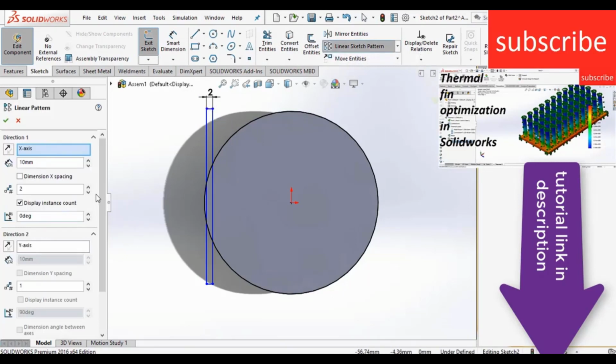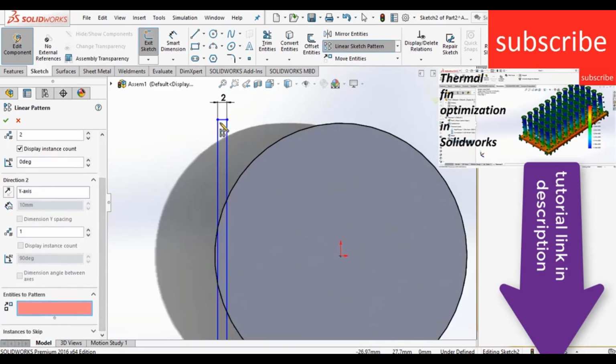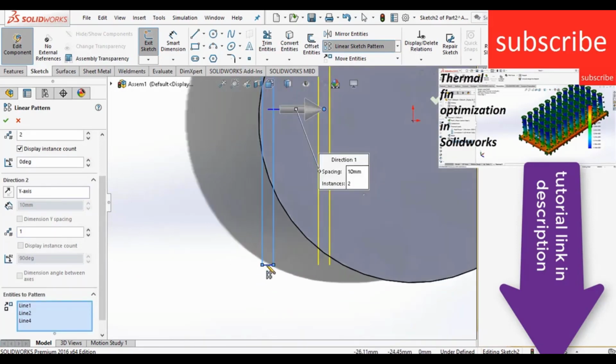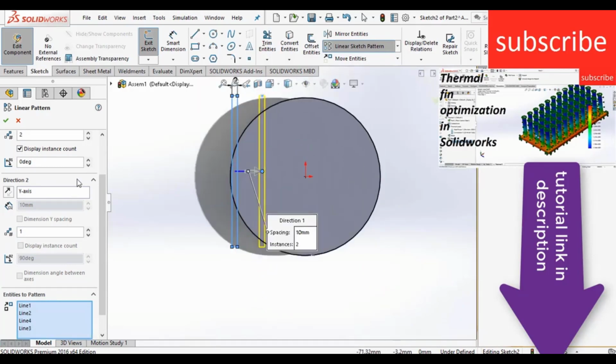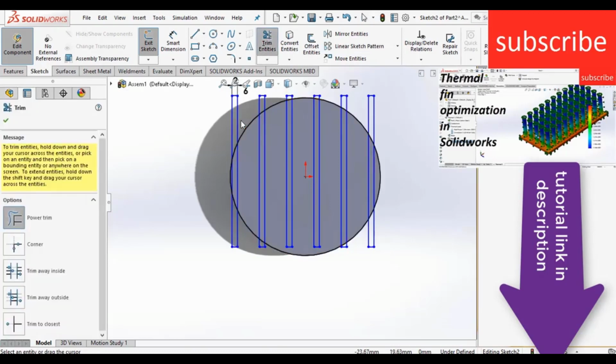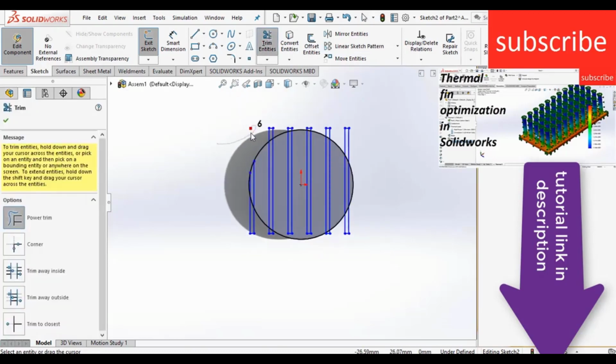Select these, move downward, select entities to pattern, and select the edges of the rectangle. Now increase the number of instances, so let's make it 6, and the distance between these rectangles is 10 mm. You can change the distance as per your requirement. Click OK. After that, click on trim entities and trim the necessary part.